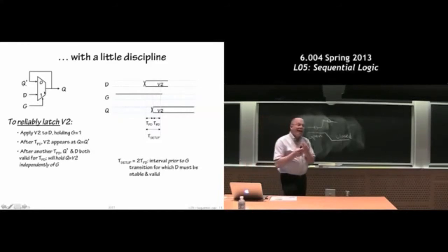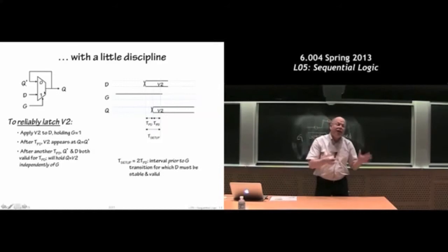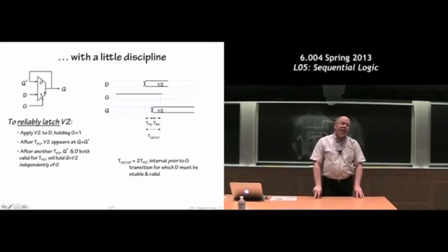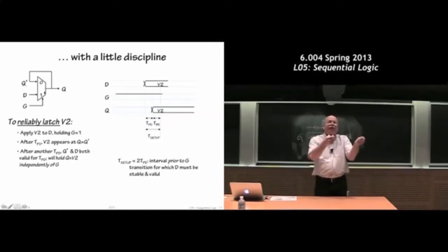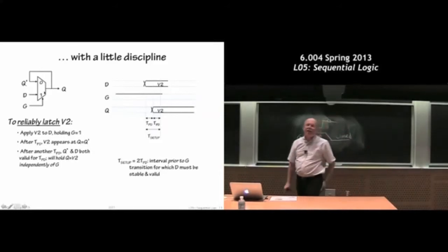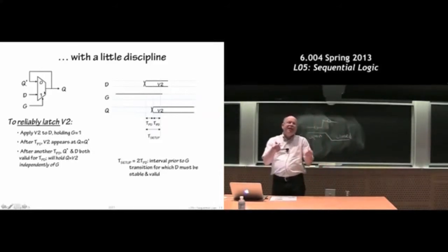Now, in fact, in many electrical circuits, you can wait a little less than that. You'll discover that if you pick up a data sheet for a latch and read about the various timing constraints, the setup time is often less than twice the propagation delay. But for our very simple timing analysis, this is the best we can do given the knowledge we have. The only thing we know about the timing is the TPD timing.